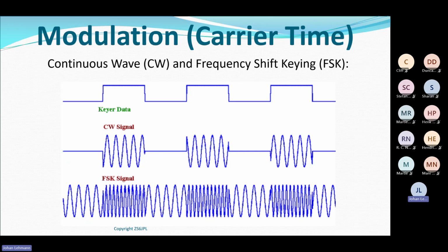What I do with frequency shift keying is I jump the frequency of my transmitter. In other words, if I look at this signal, this represents a logic 0, and we'll still get to digital systems, I think, in September somewhere. This represents a logic 0, this represents a logic 1, or this is not true and that is true.